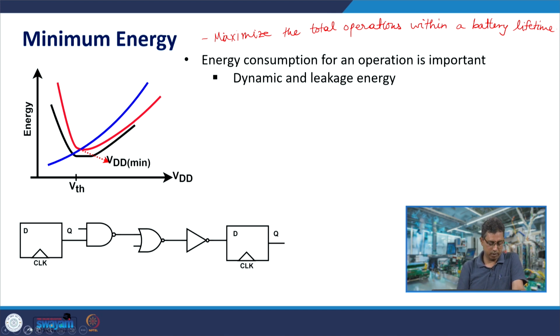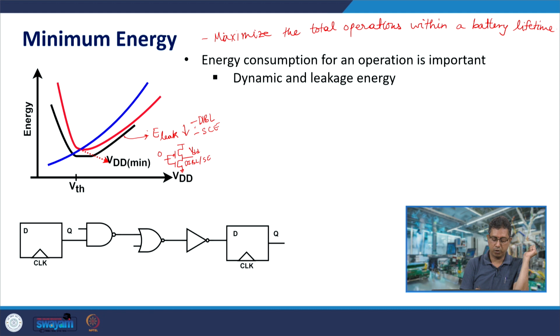As VDD reduces, DIBL reduces, and so do short channel effects. Because in an inverter, suppose the input is 0, then output is VDD. So, DIBL or short channel effects would then increase the leakage current of the inverter. Therefore, with VDD reduction it reduces leakage power.